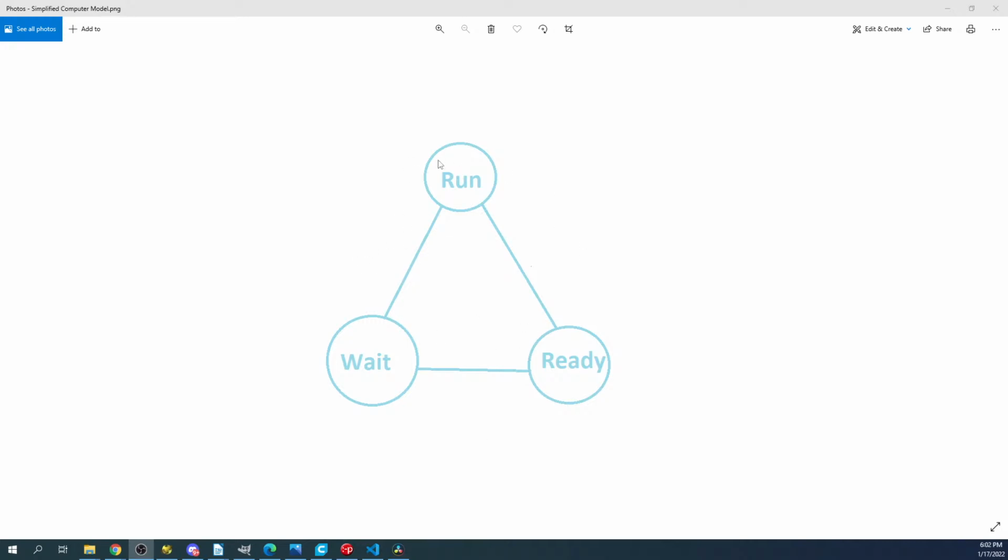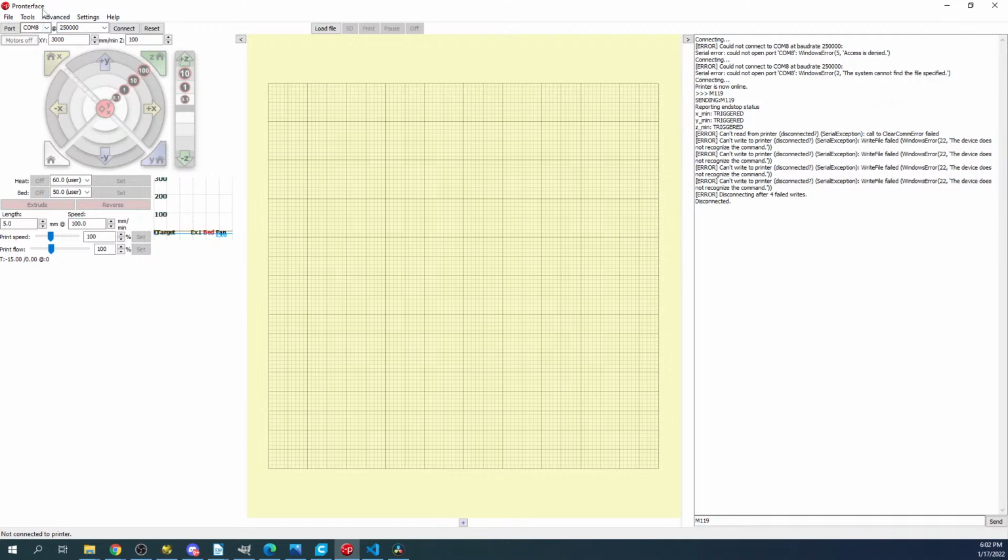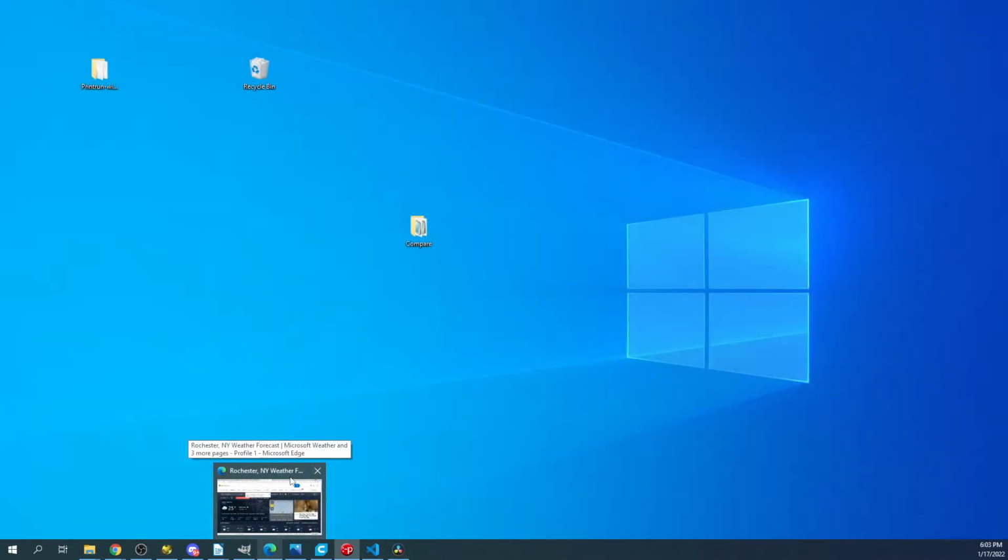If we look at a G-code file, which I'll show you how to create in a second, we can see what's going on. G-codes are also used to do analysis on what's occurring, like M119, which shows you the status of your end stops. If you were to type that in at the prompt in something like Pronterface down here, then it would execute, and that would be the run portion.